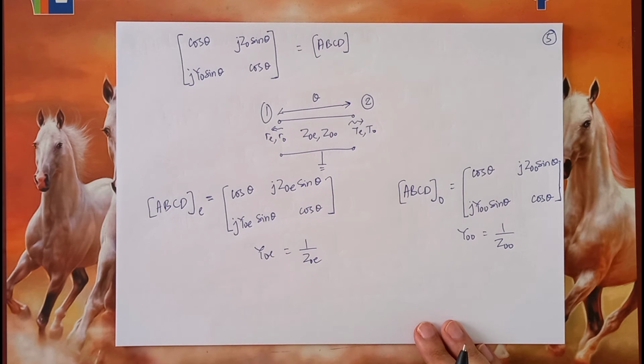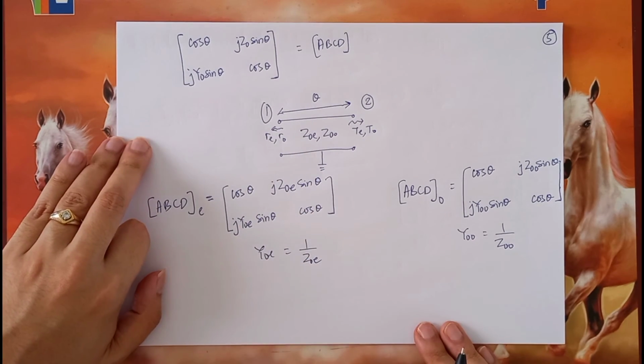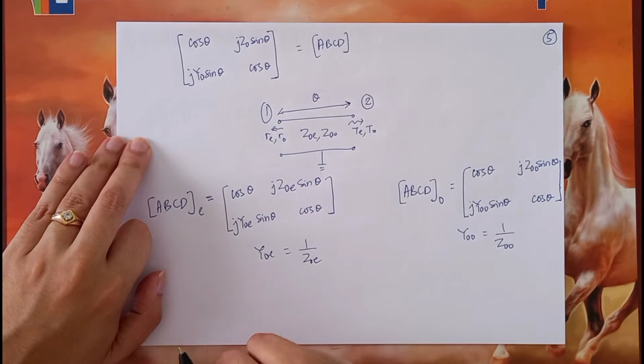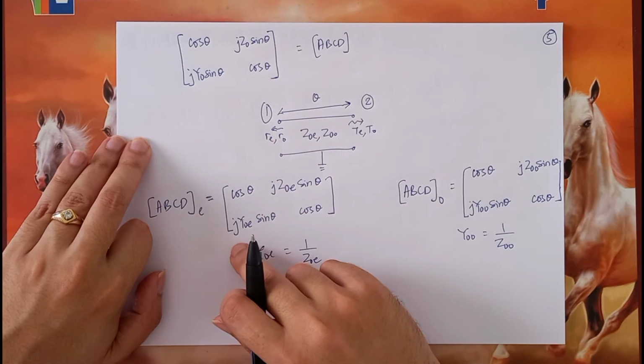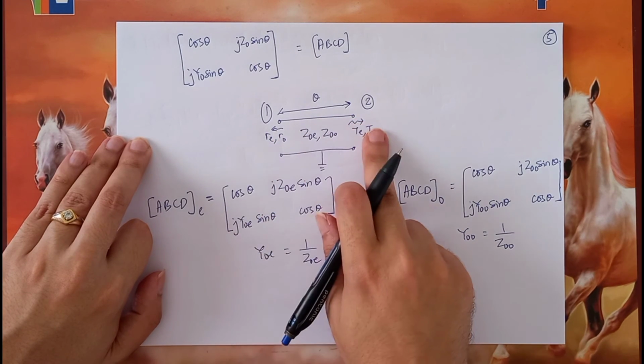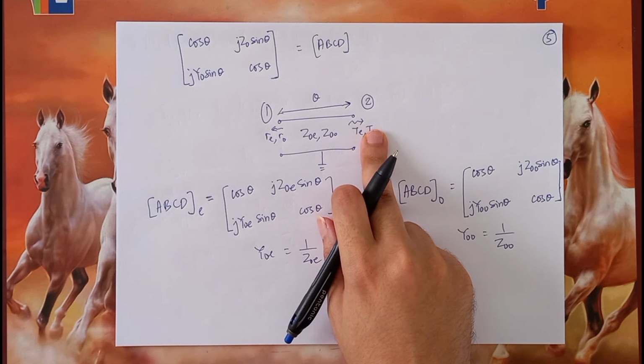So therefore, we will apply the formulae that we know to convert ABCD parameters into reflection and transmission coefficients, or the S parameters. We will not write them as S parameters because we are not denoting now the whole 4-port network, but rather we will talk only about the reflection and transmission coefficients, which are nothing but a subset of the S parameters.